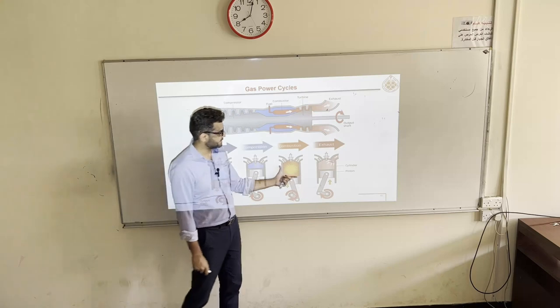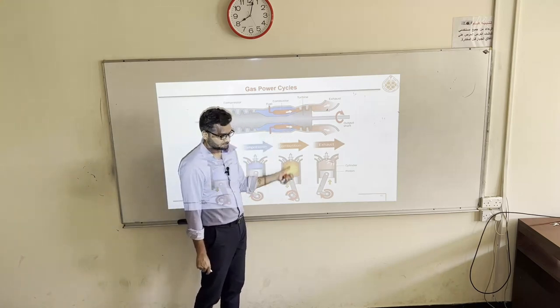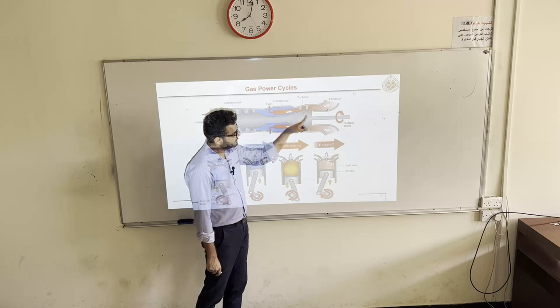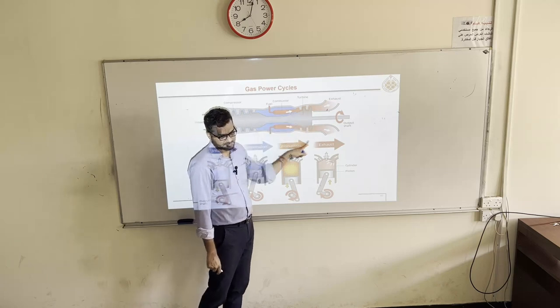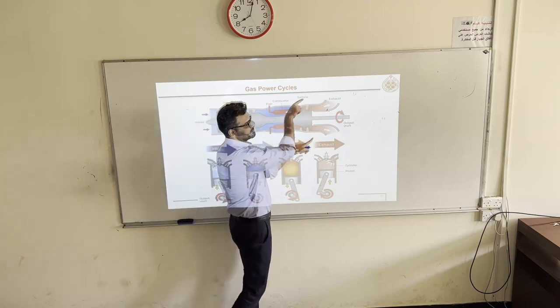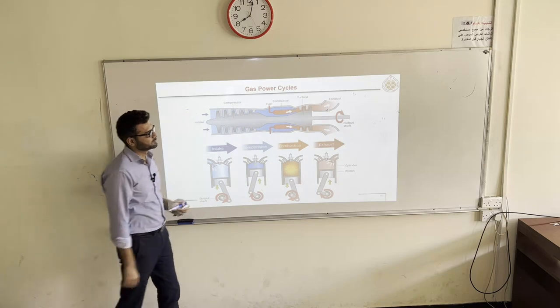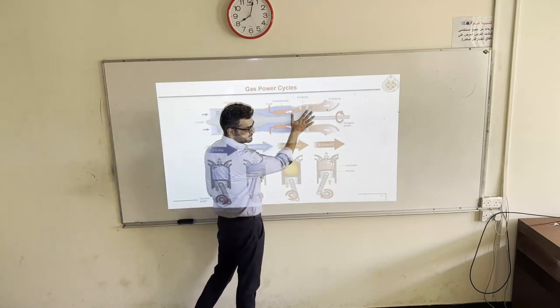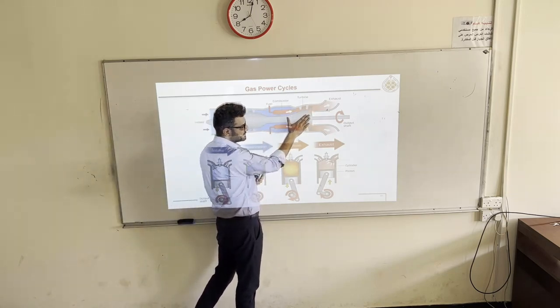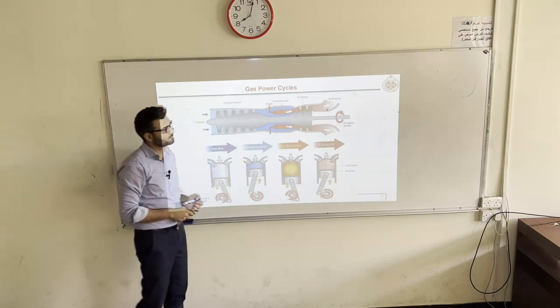So next, just like here, we have combustion and expansion. Here we have combustion and then expansion in the turbine section. So in the turbine section, now you will see area is increasing. Now it is expanding. Fluid is expanding. So fluid energy is transferred to this shaft. And this shaft is connected to the compressor. Okay.